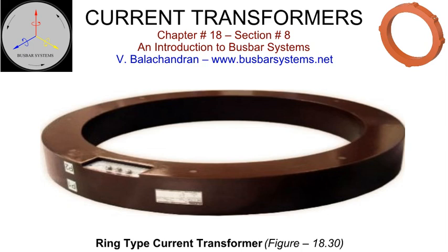Current transformers installed on insulated generator bushings are also low-voltage rated and much smaller in diameters. Current transformers installed inside the tank of a generator transformer or unit auxiliary transformers are also low voltage rated, oil immersed, and insulation is provided by the porcelain bushing. They are subjected to much better cooling and the diameters are small. Current transformers installed inside the generator circuit breaker will have air as the primary insulation and will have dimensions dictated by the diameter of the enclosure and conductor of the generator circuit breaker. The diameters of the current transformers will be large.